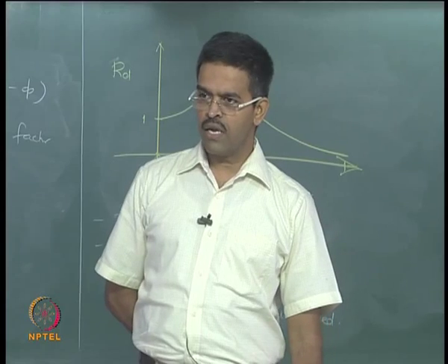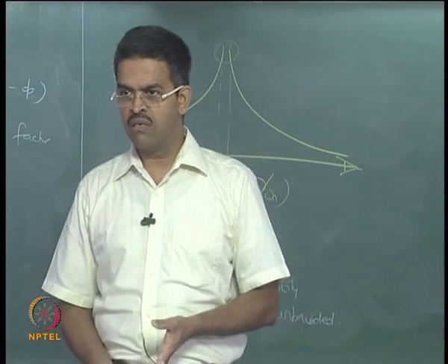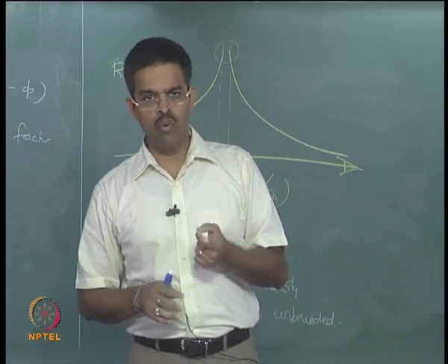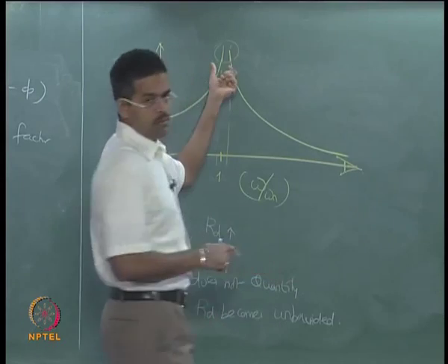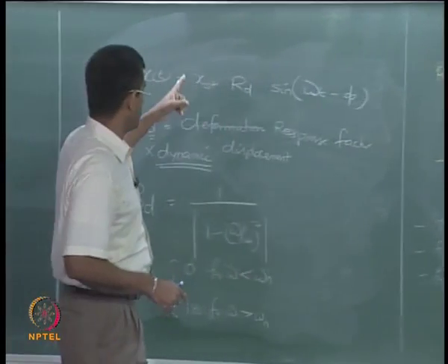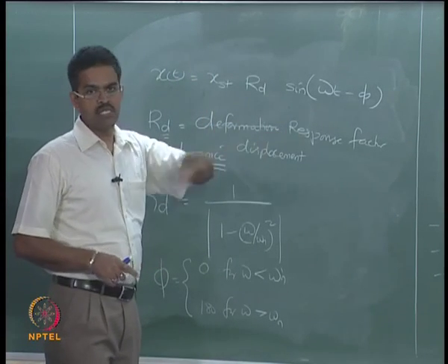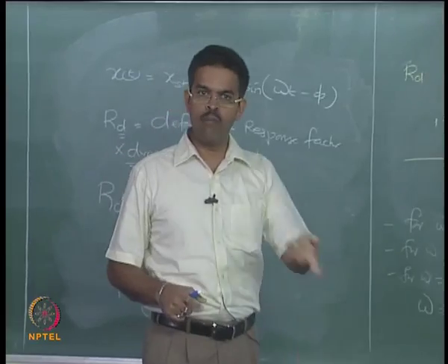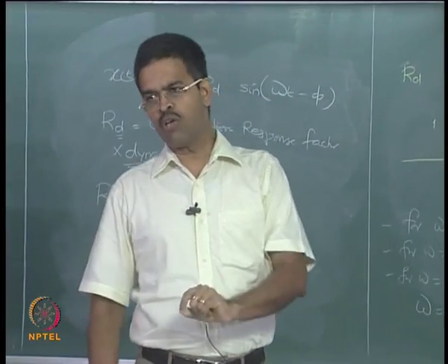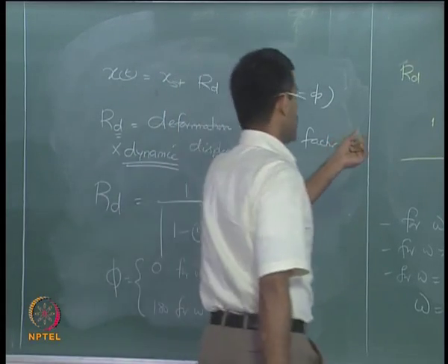Therefore, from an engineering design perspective in offshore structural design, we need not bother about the resonant condition in the design, there is no worry. But mathematically I must know what happens in this domain, it is very important for me. But I cannot use this expression because this expression was derived from a fundamental observation where the condition is never becoming valid. So, I must go back to my original equation and derive it again, substituting omega equals omega n and see what happens. Then I will discuss this band at which it is happening.